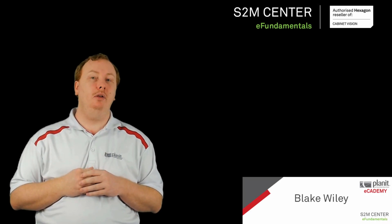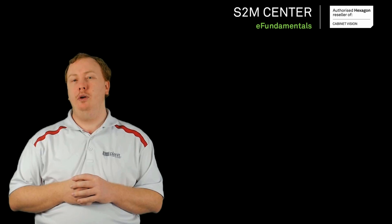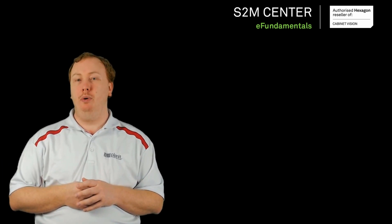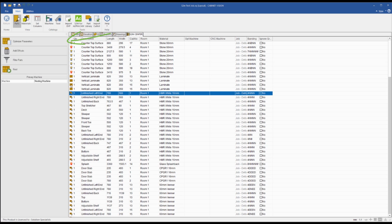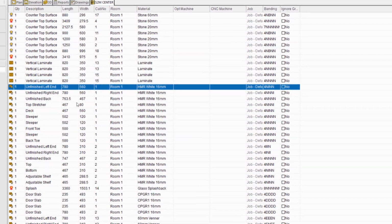So now that you've set up your system preferences, it's time to take a look at our optimize parameters. This is where we can set up a few rules that the S2M Center will use when it's taking your part list and placing all the parts onto your sheets of board. You can access this section by selecting the Optimize Parameters option from the top of the sidebar while in the Parts and Materials view.